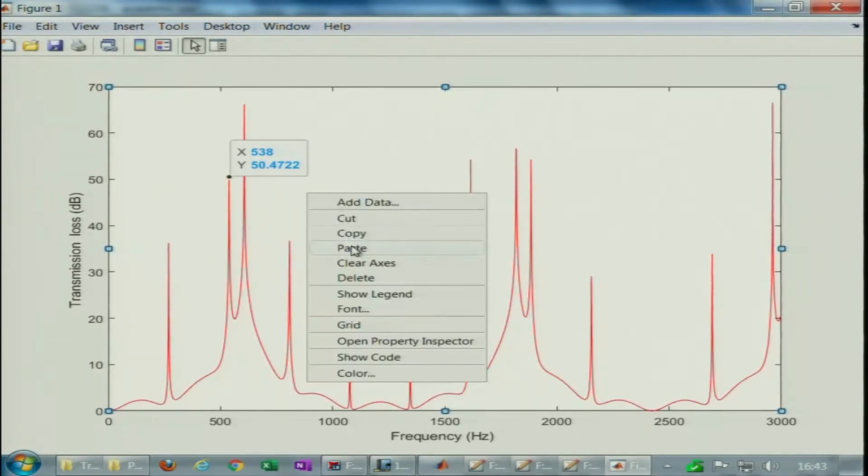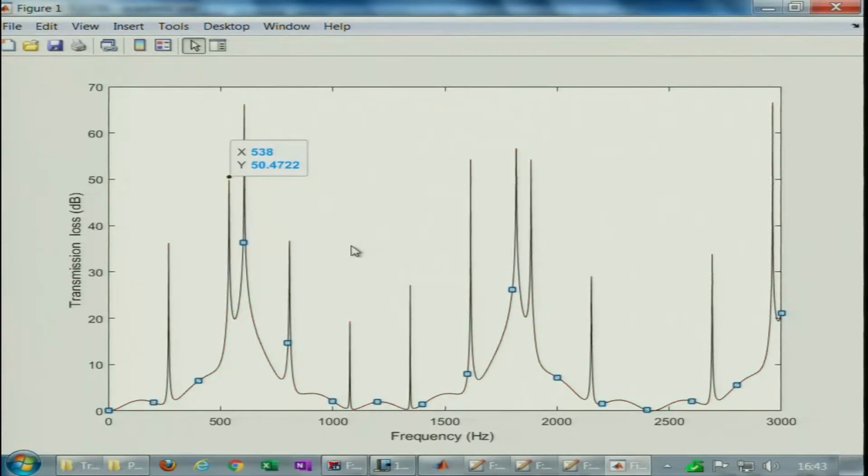So, this is what I have taken out and pasted again. We are getting multiple resonances due to destructive interference, and there are some troughs also occurring because of constructive interference. There are frequencies at which the entire acoustic power is transmitted as it is. These are all part of multiply connected mufflers, and there are a large number of such connections. For example, what I am going to probably talk about in the next class perhaps are some connections which are much more intricate, much more complicated.